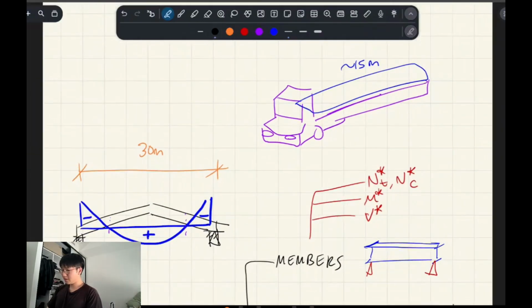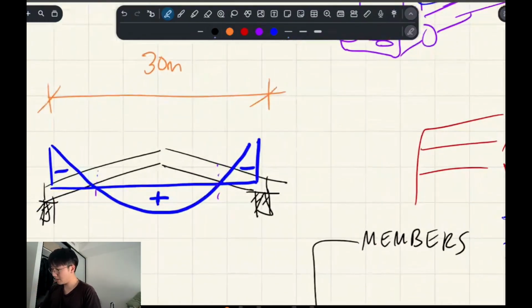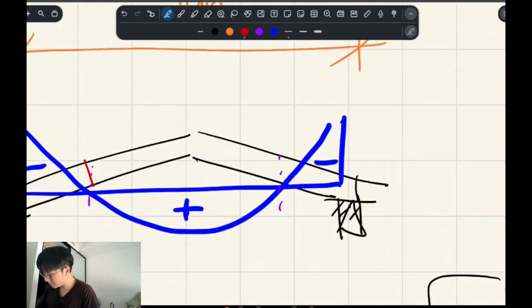So you basically have to split up your beam. If you were to split up your beam, you would split it up where you have zero bending moment, so these connections aren't being stressed as much. And you basically want to design your end plate to end plate connection with really strong bolts, so that the entire thing is able to carry these bending moments. So going back to the plates, how you might do a 3-plate splice.